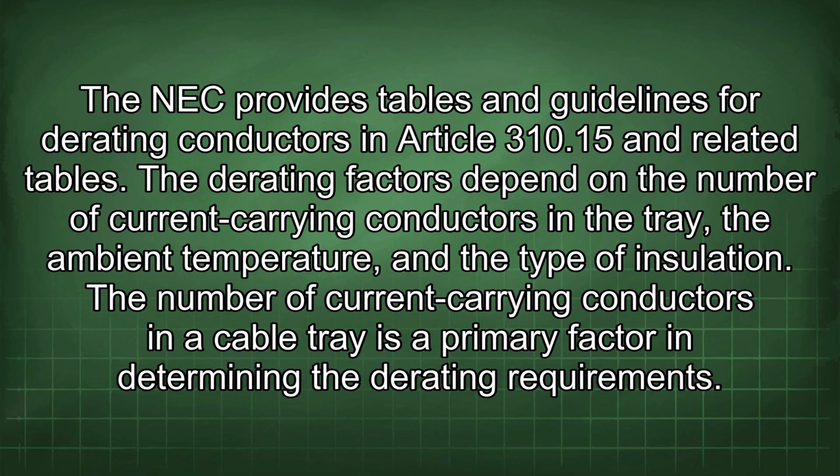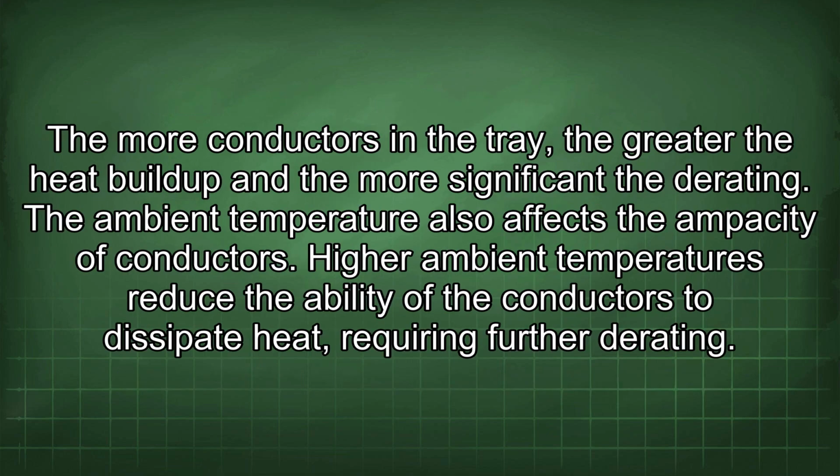The derating factors depend on the number of current carrying conductors in the tray, the ambient temperature, and the type of insulation. The number of current carrying conductors in a cable tray is a primary factor in determining the derating requirements. The more conductors in the tray, the greater the heat buildup and the more significant the derating.